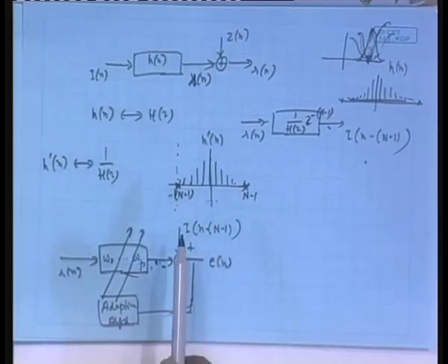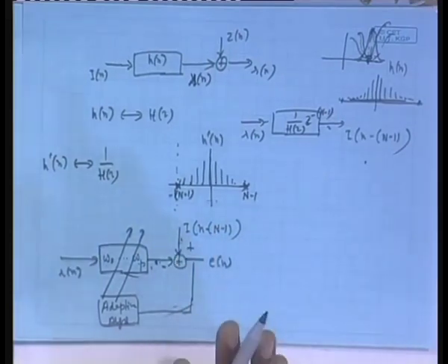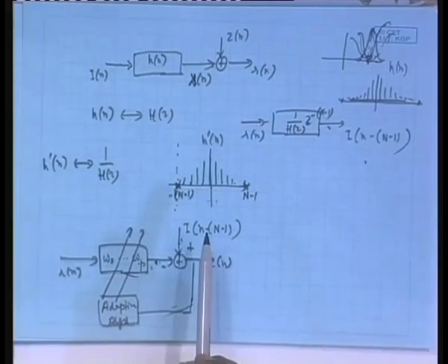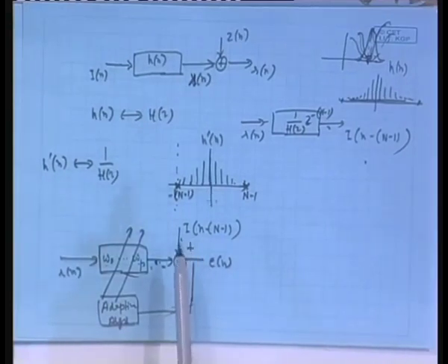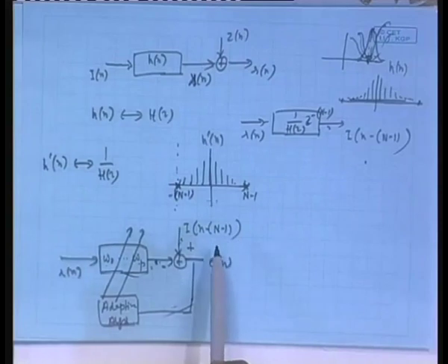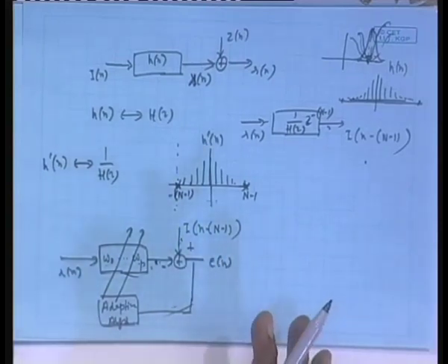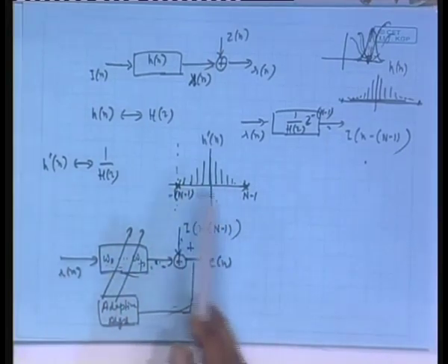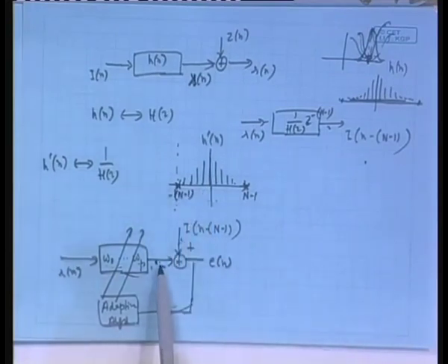Once it has converged, and sufficient training time has been given, normal business starts again. The transmitter no longer transmits the pre-designed training sequence; it transmits normal sequences. But now I can trust that the channel will not start fluctuating, at least for some time. So, these converged filter weights will indeed represent that ideal equalizer, and whatever I get is indeed the one that is transmitted.